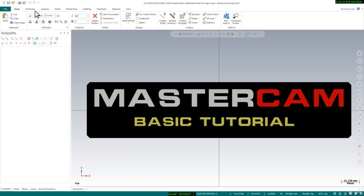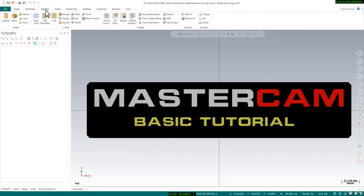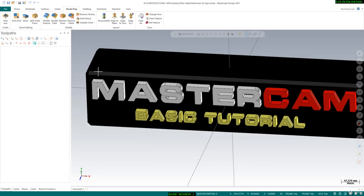In the wireframe tab you can do 2D designing, like using the line commands, the circle commands, and the rectangle commands. You can create letters, trim, break, extend. All the commands you will get here, and after that you will get the surface commands. In these you can do surfacing, surface modeling, solid modeling, and in the model preparation tab you can do basic changes, like if you have to push-pull this part or change the dimensions, then you can easily use the model prep option.